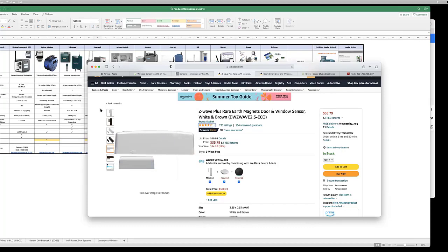So if you were counting, you would want to do all the counting on the edge device. You would want the total count reported back once a day or once an hour. You wouldn't want each individual count to be reported back. You would store that on the device and then report it every so often. That way, if you miss a pulse because of a forklift driving in front of the radio, maybe it's a line of sight communicator and the line of sight is broken for some reason, you're not dependent upon your count being transmitted every millisecond.